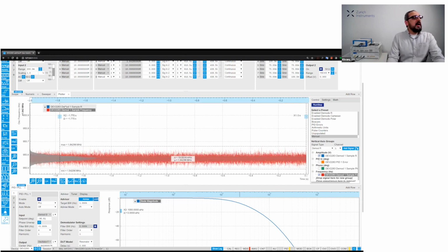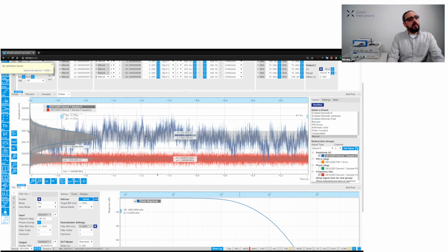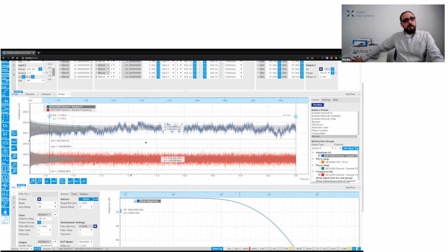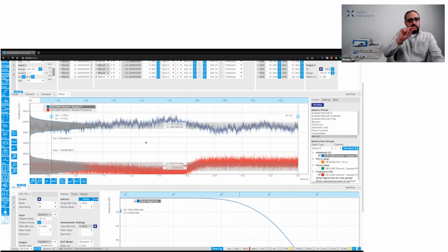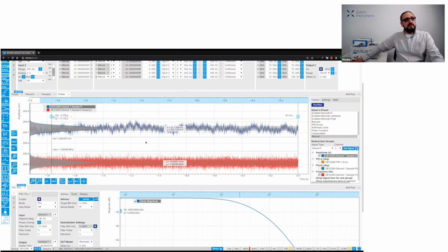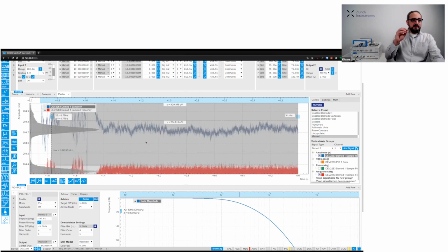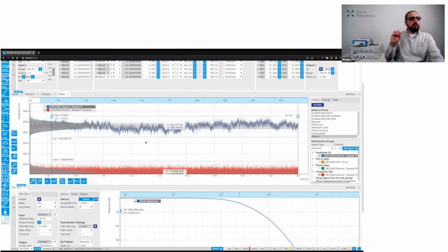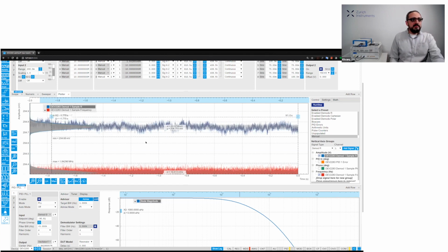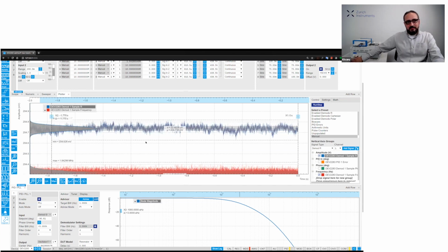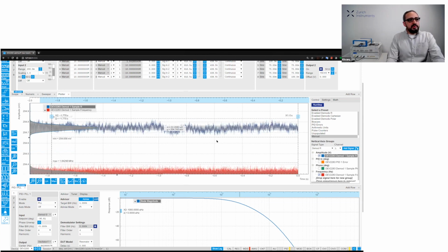But now let me also grab the amplitude of this measurement. You can see that it is fluctuating quite a bit. If I tap the resonator, it feels that, of course, and the frequency recovers, but the amplitude doesn't recover that fast. It can even go to another arbitrary state because I'm not controlling its amplitude. Look, now it is actually drifting. What I'm doing now, to one extent, is using this oscillator as a proximity sensor. But to make things a bit better, we need to also close the loop for this amplitude.